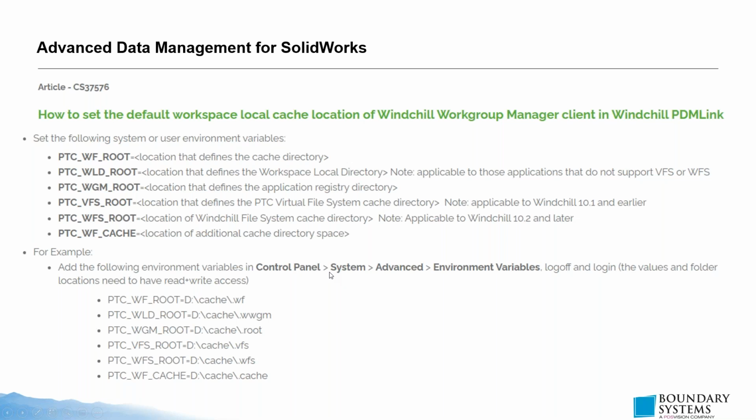This is once again set up in the environment variables. So I will go in and show you, if you're not familiar with where that is, I'll go through and show you that as well. They do have a path here: control panel, system, advanced, environment variables, and you simply go through and set up the name and then the value of that name. And you simply go in and set up where that information is. As you can see, it is using a common directory, which is a cache directory, and then just the extension of each one of those variables from above.